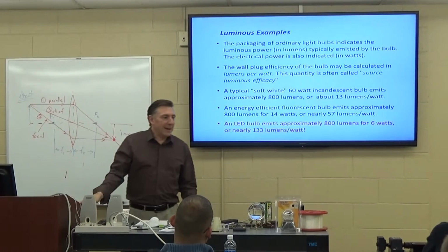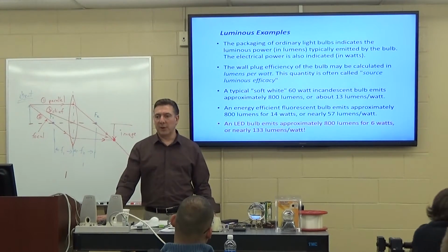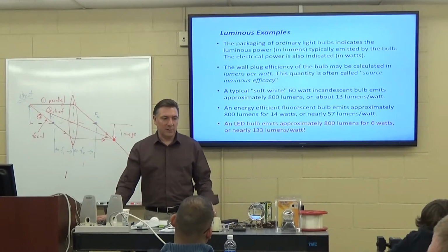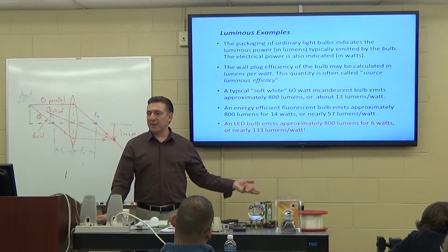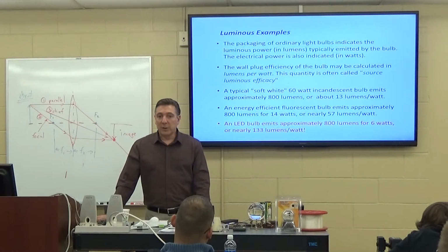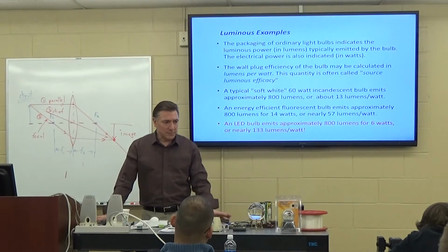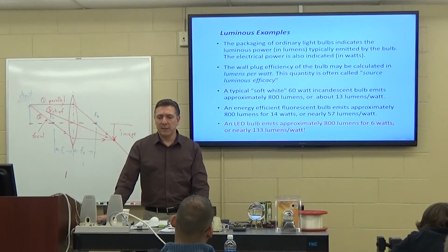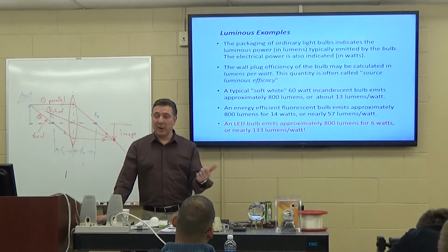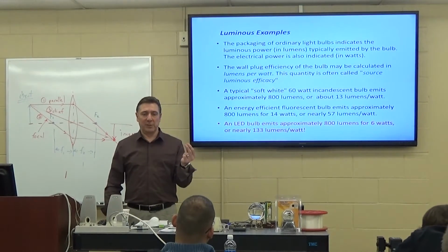Good segue. So the cool thing about LEDs, which is difficult to get in a fluorescent bulb, is that if you look at, and this is for those of you who did the lab on Tuesday, and the rest of the people who do it today, we look at the spectral content of these light bulbs. The LED bulbs are called multi-chip emitters. They have 3 different LEDs in them, a red, a blue, and a green. You combine red, blue, and green, you get white, okay? But you can get these that are tunable. You can change the hue, the color temperature of the bulb.